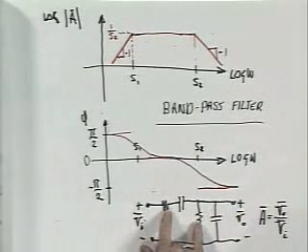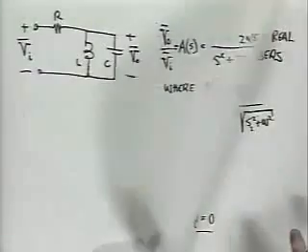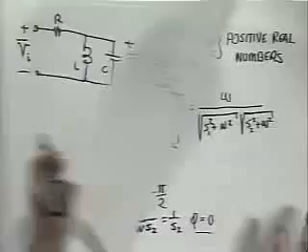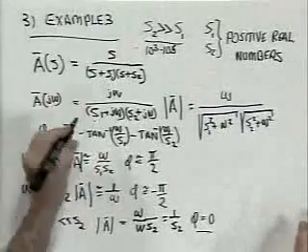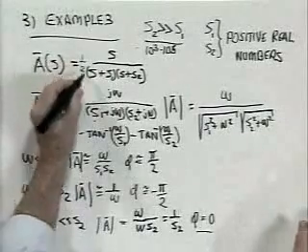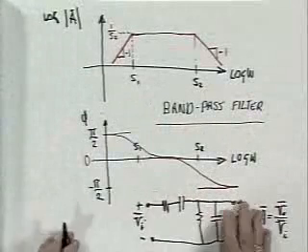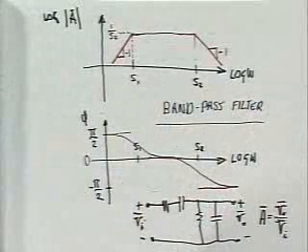These two resistors form the arms of an equal arm voltage divider. So if I'd wanted to be more precise about this third example, I would have added a constant out here, which is 1/2. But that was just going to get in the way in terms of these drawings. That's the circuit that will produce this with the factor of 1/2.